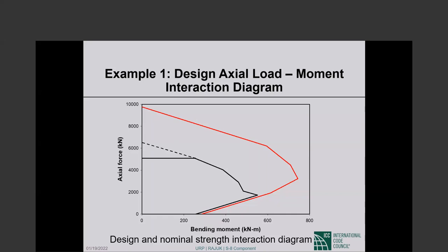Spiral is definitely more effective, if by effective you mean how well it confines the concrete. The pitch of the spiral is typically closer than the kind of tie spacing we use for circular ties, and that also obviously increases the effectiveness.